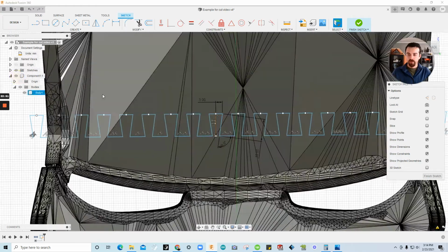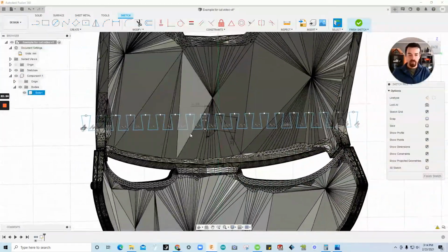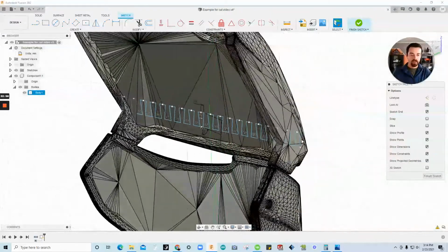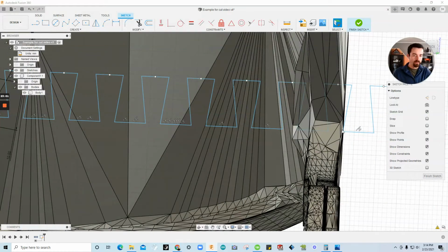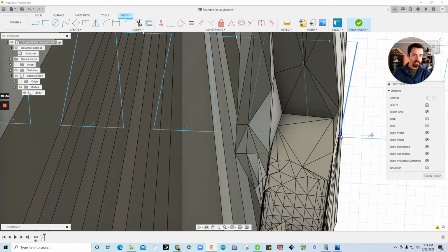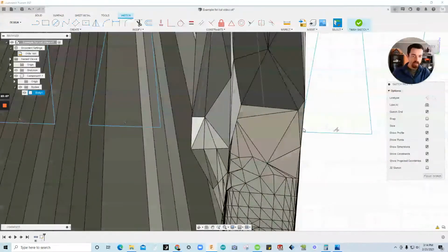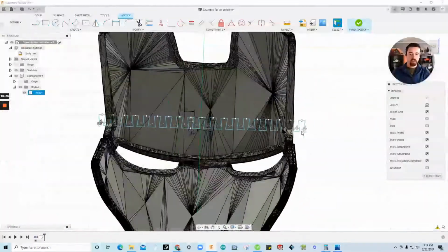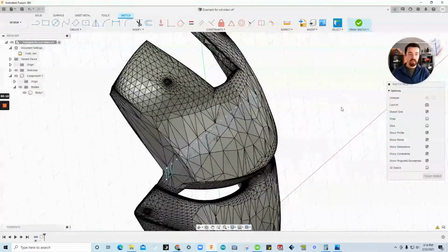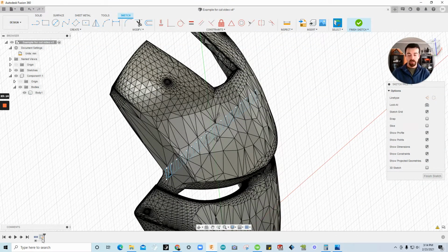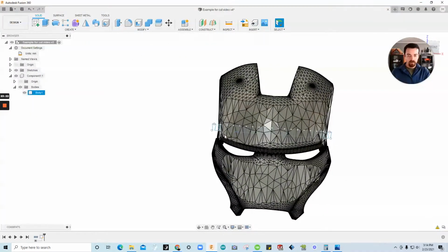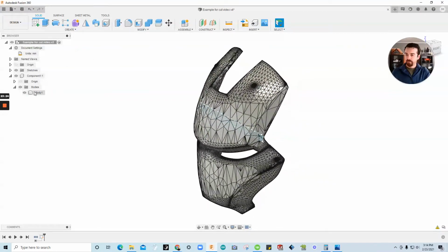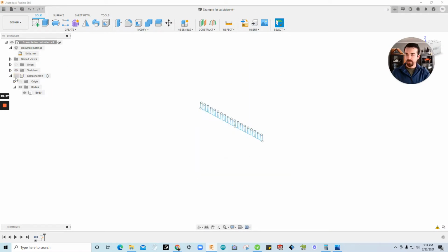Let's go ahead and turn on our component visibility to view this. One problem you might run into is accidentally cutting a small piece off. Like if we left it like this, as that line goes in a little bit, we'd probably have just a tiny piece of body cut. But I'll actually go ahead and make that mistake with y'all, so I can show you that we're working with a nice model now, and we'll be able to go back and edit that. So let's go ahead and make it. So finish sketch. All right. For now, I'm going to turn the visibility back off on the component.